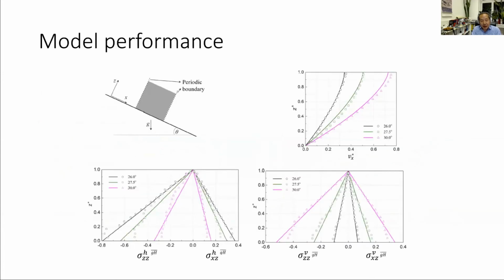And we put that whole thing in SPH and simulate this kind of very long slope sliding down. You could see here how it is for different angles, for slopes of 26 to 30 degrees. We have a look here at Z, normalized with the depth, and at what kind of stress we have. You see here we got a total stress, and here H is the inviscous stress, and V is the viscous stress.